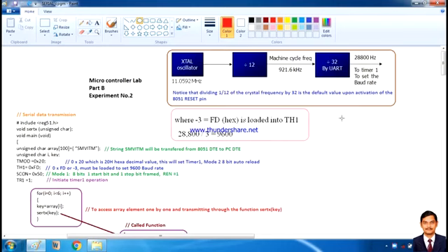I have to achieve the speed compatibility. So for that sake, we have to use an internal timer again, and we have to move a particular value so that I can get the specified baud rate. So this calculation is used here, and this value we are going to move to the respective timer. In that sense, it is going to create enough delay to transmit each character by character, and it maintains the speed.